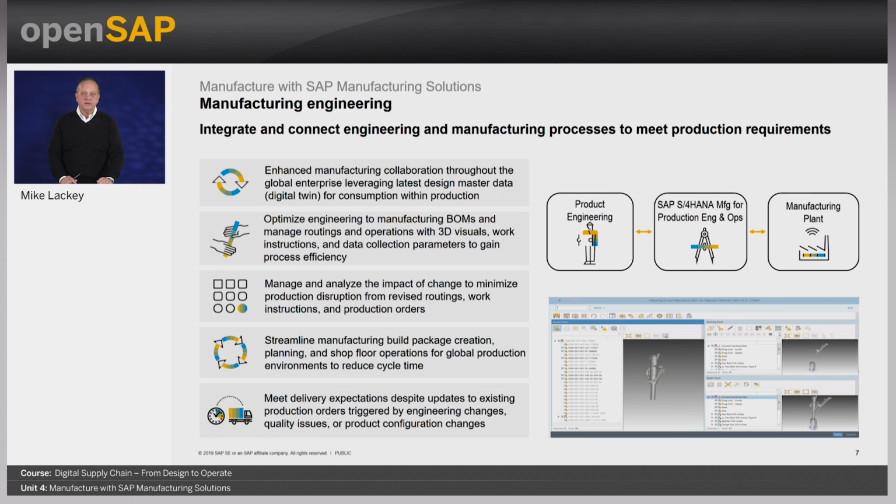Let's start with manufacturing engineering. The handoff from engineering to manufacturing. Taking an EBOM. This is all the components you need to design this product. This is what goes into the product. And turning it into an MBOM, a manufacturing BOM that is structured the way you're going to manufacture, that maximizes the ability to control cost, maximizes quality, and maximizes your ability to deliver on your demand. It's no longer about capacity, it is about the ability to deliver the demand signals that you have today, agility